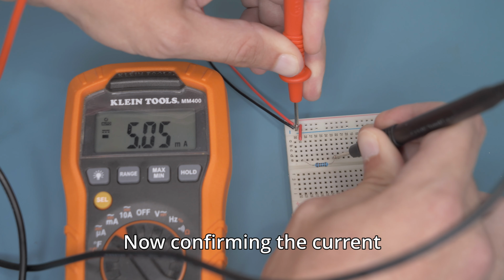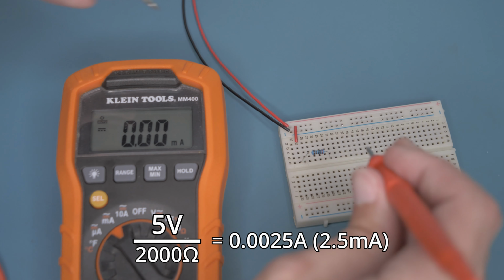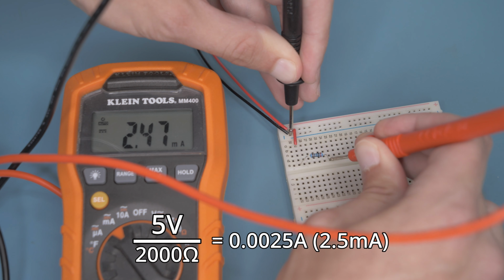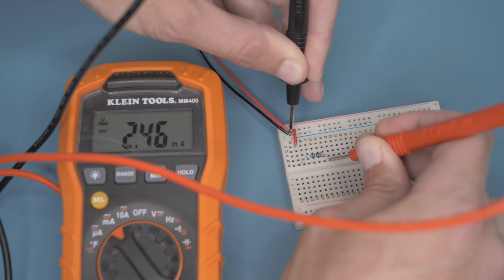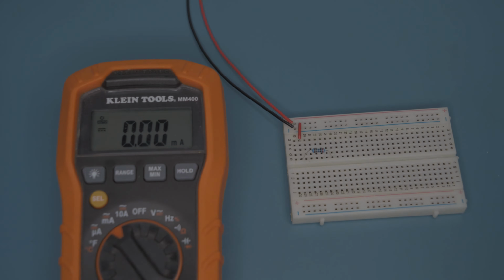If I swap out the 1 kilo ohm resistor for a 2 kilo ohm, our new current will be 2.5 milliamps, half of what it was before. So we can clearly see that the relationships between voltage, current, and resistance are linear. If we double the resistance, the current will halve. If we halve the resistance, the current will double, and so on.